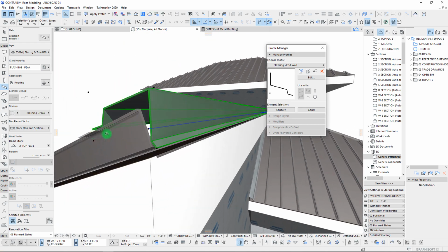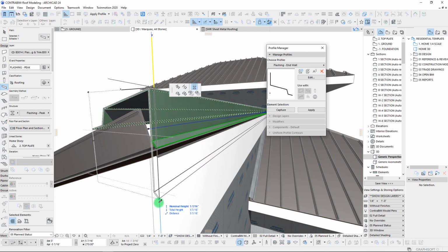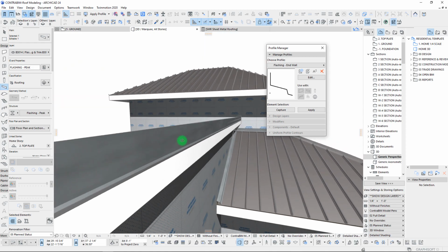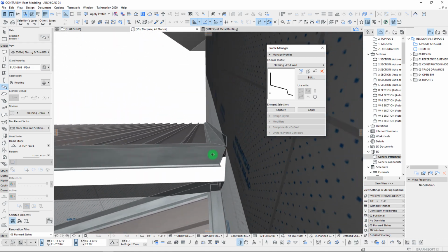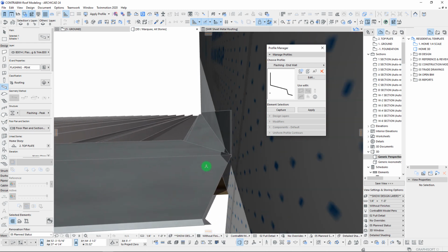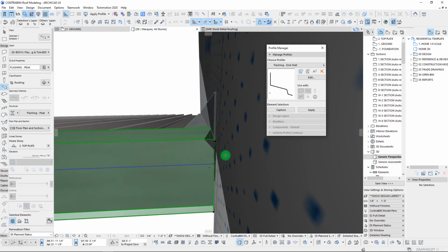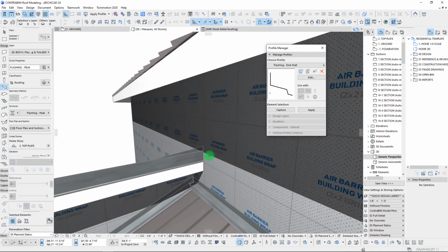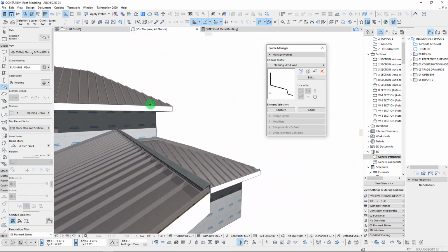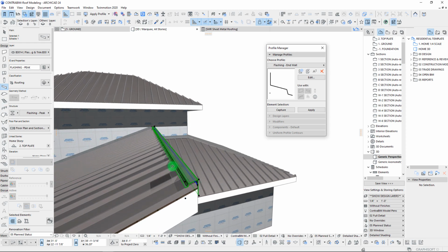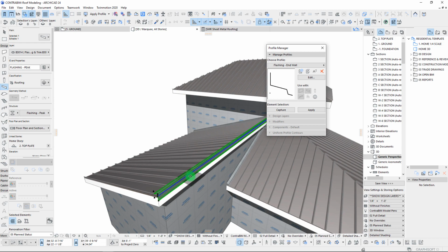And then of course, because we have this as a stretchable profile, we can take this and start pulling that down. So okay, that looks pretty good, except for we are starting to miter here. If we take this, pull it back just a little bit, you can see how those clean up much more nicely. So sometimes we want to just get out of our intersections there, and we can do that by shortening or lengthening certain parts and pieces. So okay, that's really our only peak.